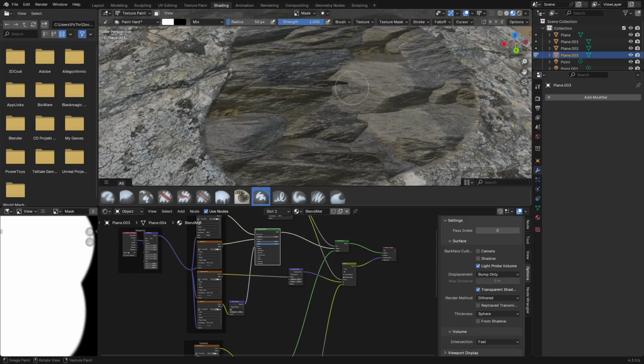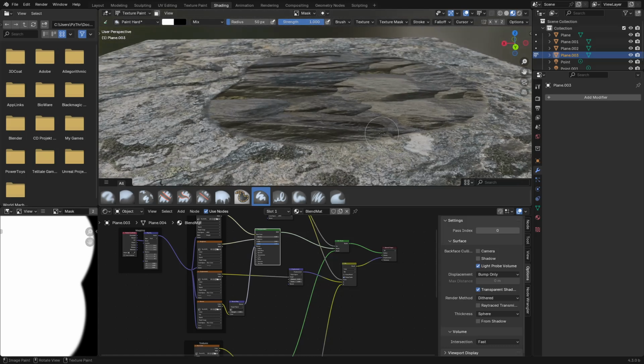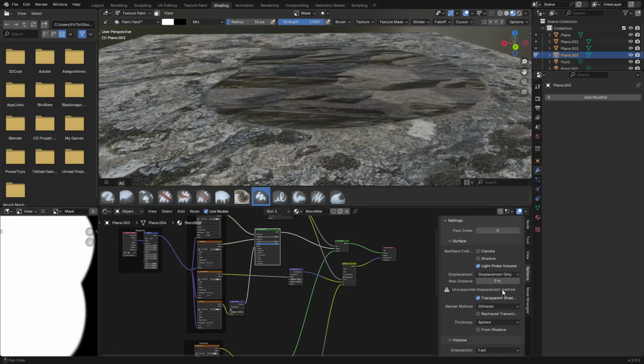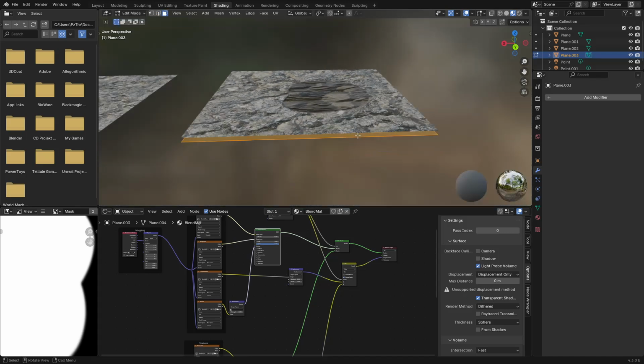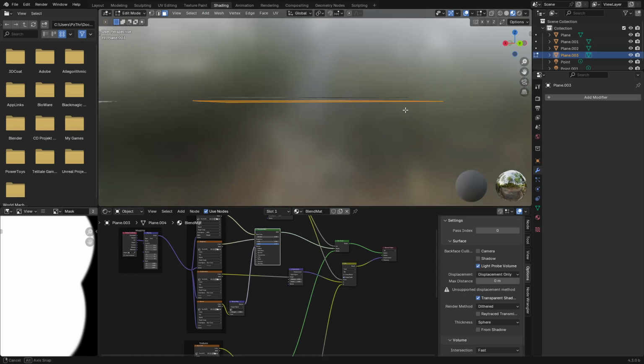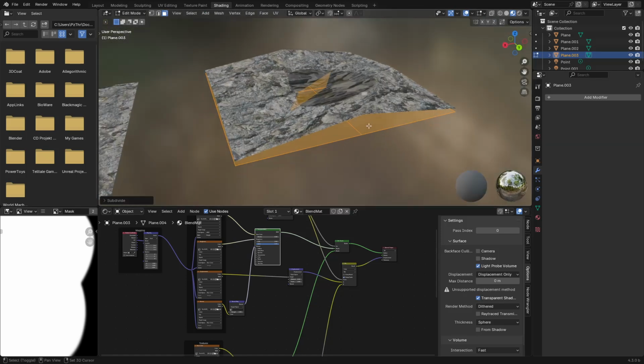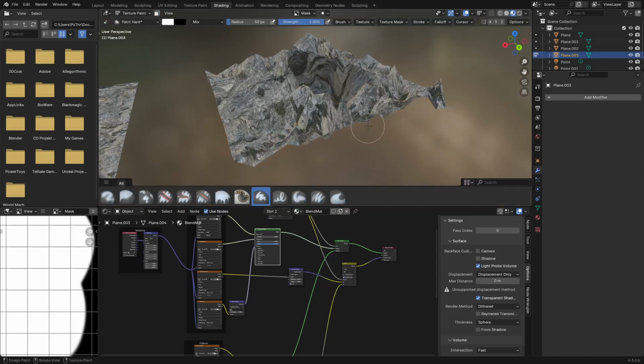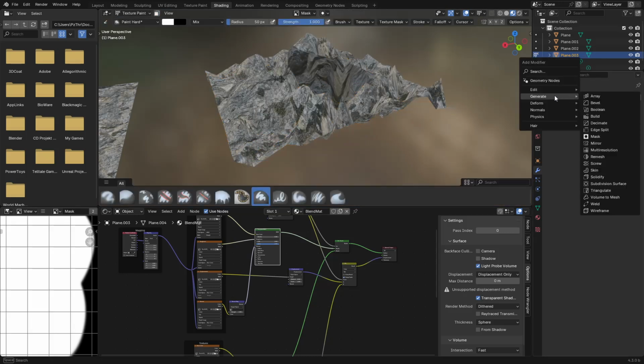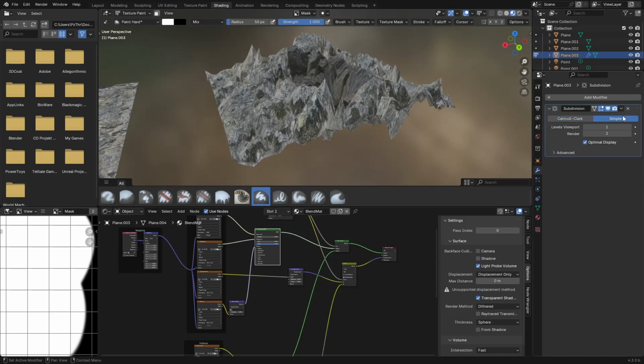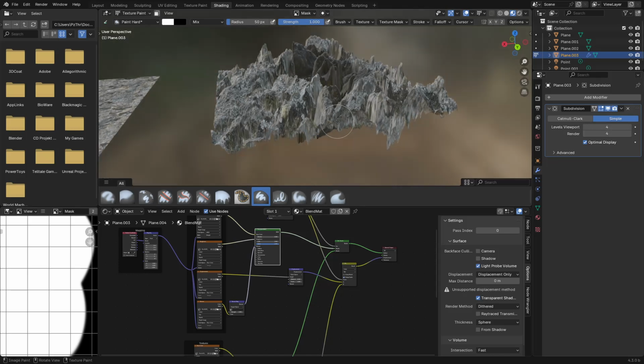There are ways of doing height blends and things like that, but for now, we got this going. It's not too bad. We'll kind of run with it. It's set to bump only. Set it to displace, and you'll probably have it go crazy more than likely. Oh, we also have to subdivide it, right? So right click, subdivide, hit Shift R a few times, add the modifier, subdivision modifier. Simple, we'll bump up the local for now and render.